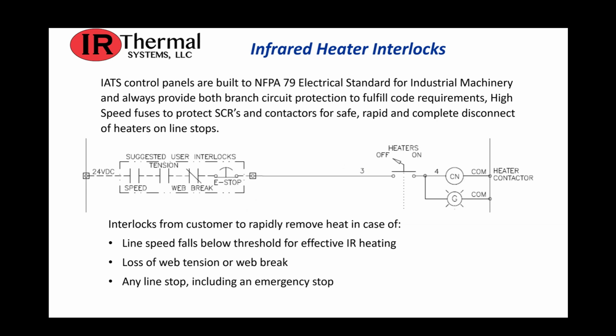So we also include interlocks, heater interlocks. Our control panels are built to NFPA 79 electrical standards for industrial machinery and always provide both branch circuit protection to fulfill code requirements, high-speed fuses to protect the SCRs, and contactors for safe and rapid and complete disconnect of heaters on line stops.